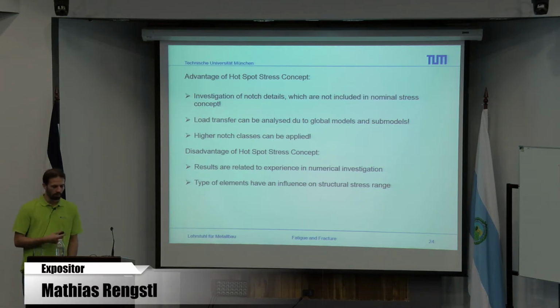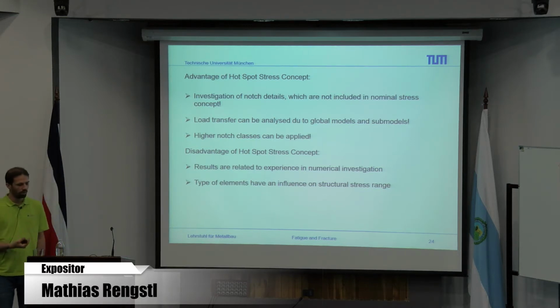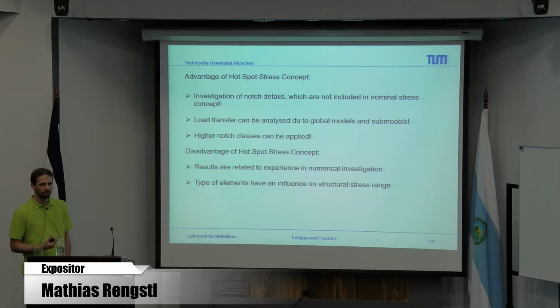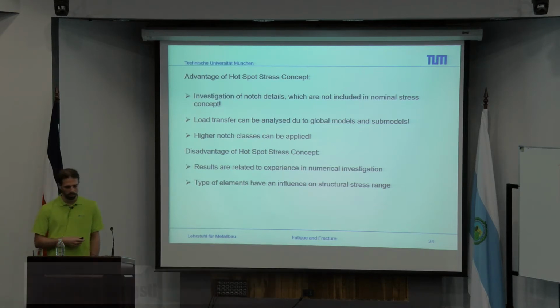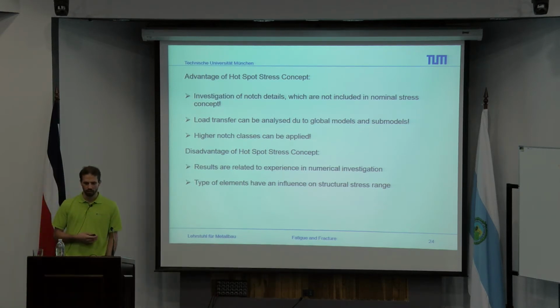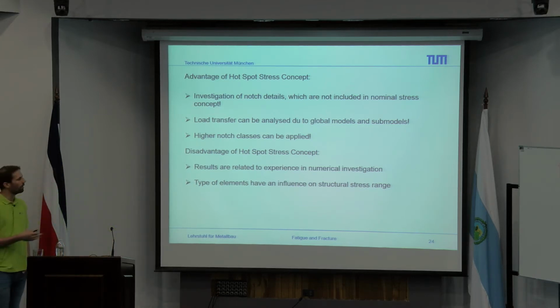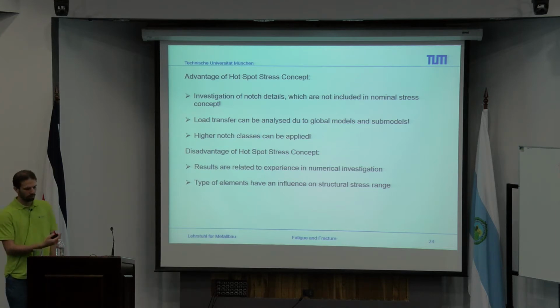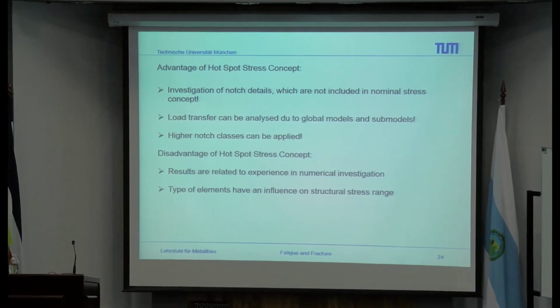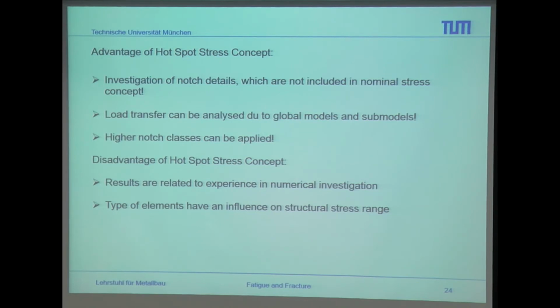And of course, the disadvantages are that the results are related to the experience in the numerical investigation, and also the types of elements have an influence on the structural stress. So, for example, if you calculate the same system and you just switch the definition of the shell element, at the end your results are going to be different.